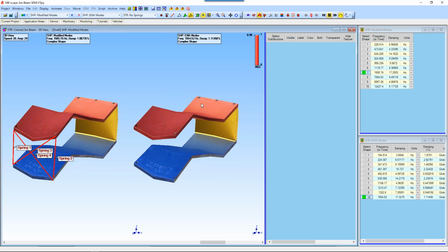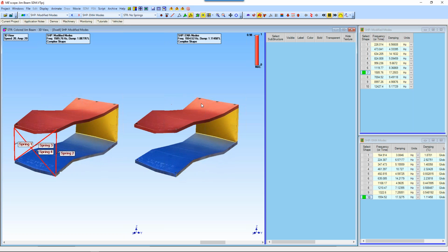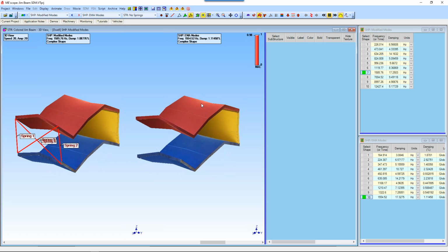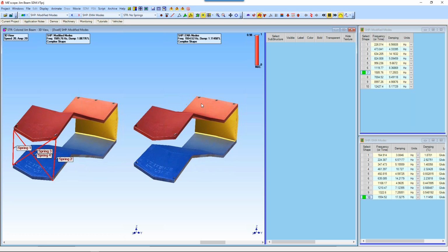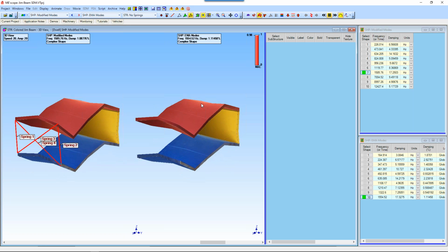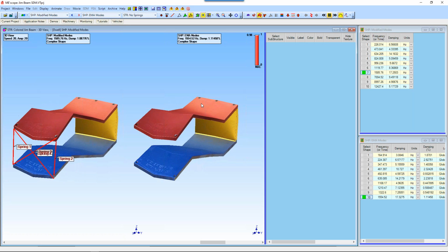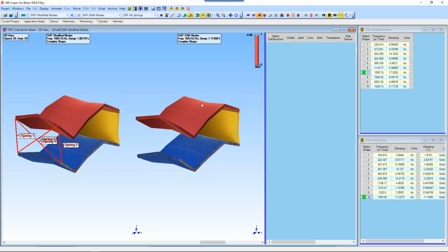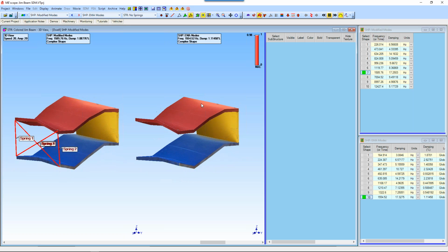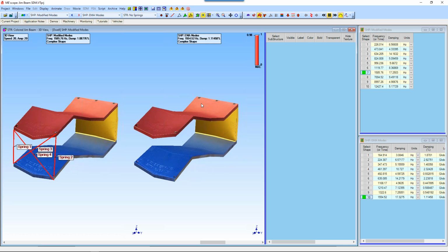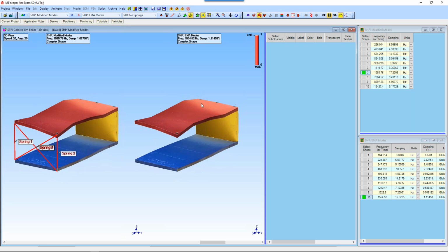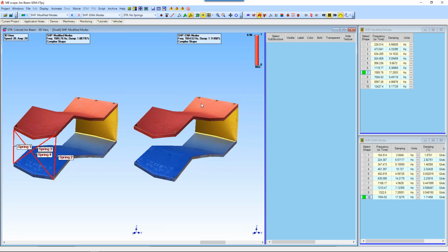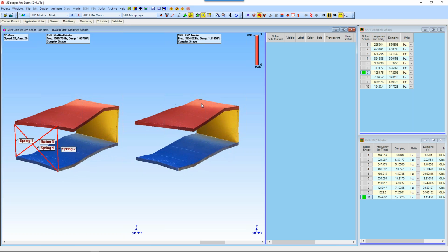We could get into more sophisticated modifications, but SDM pretty much works the same way no matter what we give it. Sometimes we can work with just a couple of mode shapes in our modal model if in fact they represent the dominant dynamics of the machine or the structure in the frequency range that we're interested in investigating. Here we went out to 1500 hertz. There are many more modes in this structure beyond 1500.